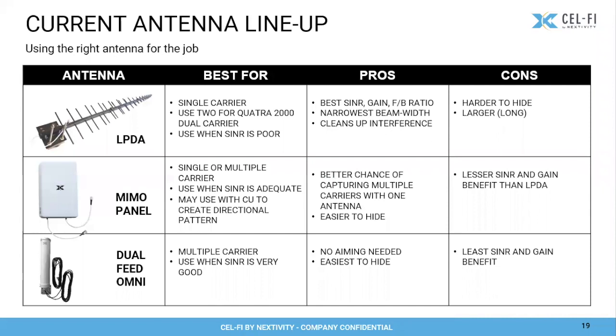If you look up the term Fresnel zone, the transmission pattern between a transmit and receive antenna is actually a parabolic region between the two antennas. Something that enters that parabolic region, even though it isn't blocking your line of sight, will actually have an effect on the energy transfer between the two antennas.